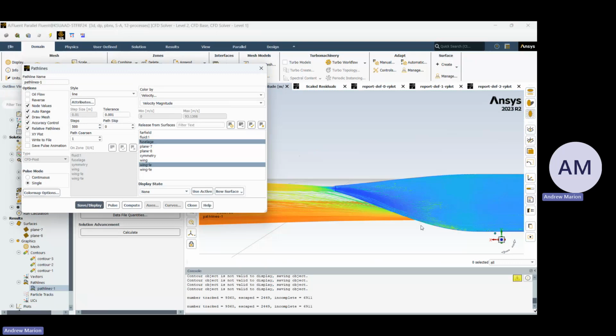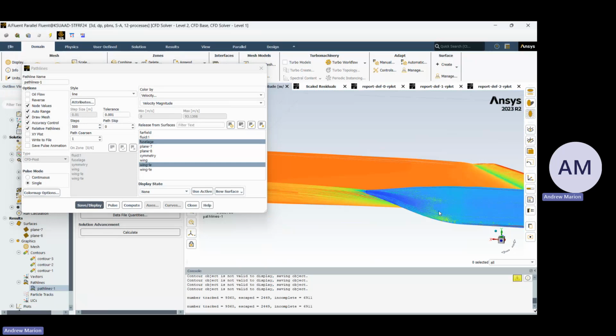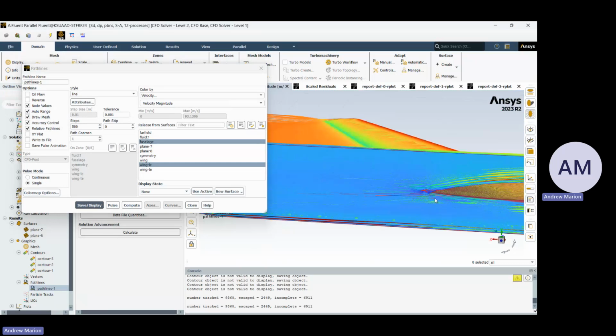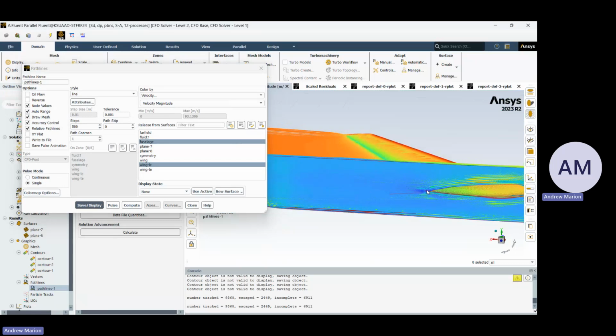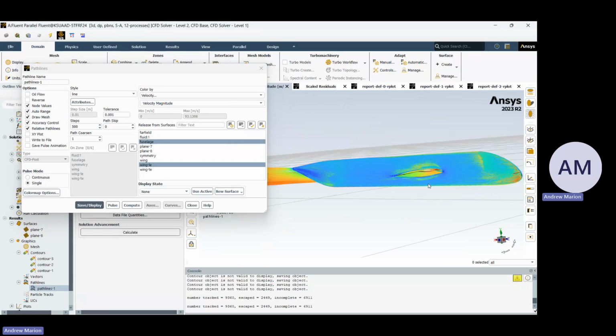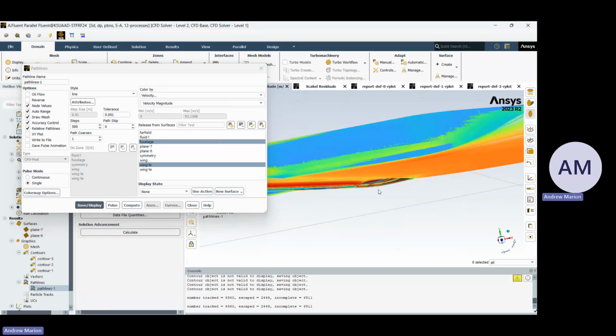separate. Because flow can follow a smooth edge without losing energy and falling off. But when you have a sharp drop off like that, the flow separates, and that's what flow separation is. I'm stressing that this is really bad, but due to how well swept this is, compared to the entire aircraft, it's actually not that bad. But if that truncated area was any bigger, it would be creating a larger and larger vacuum suction at the back of the plane.